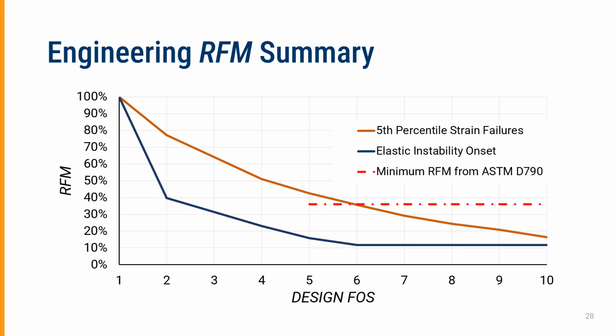When it comes to any of the other samples where we've had a structural requirement for the FRP, the lowest that we've ever measured was 36%. And believe me, it was in very poor condition. It was not structurally sound. So we're using this as the minimum practical limit.